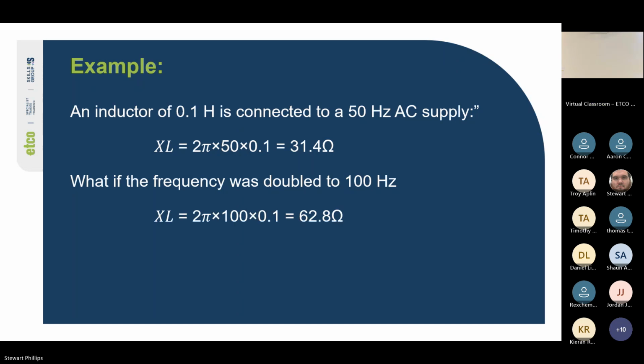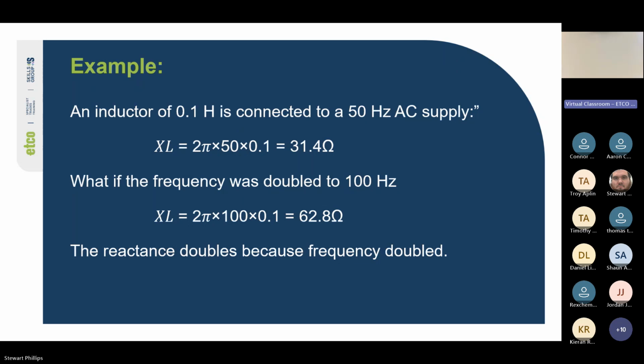Yep. So basically, we've doubled the reactance by doubling the frequency. By only doubling one thing, we've doubled the entire reactance. So when we double the frequency, we double the reactance. Pretty straightforward, right?